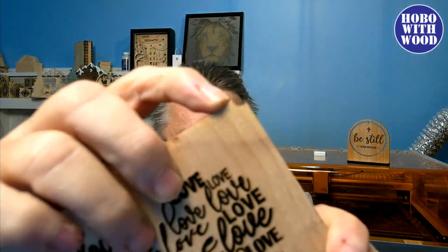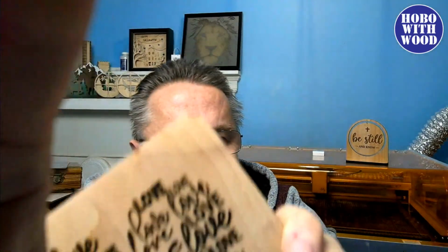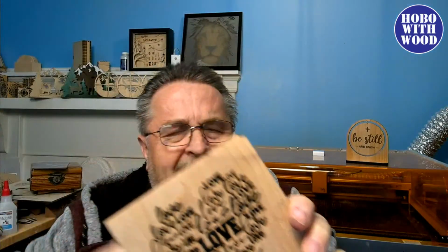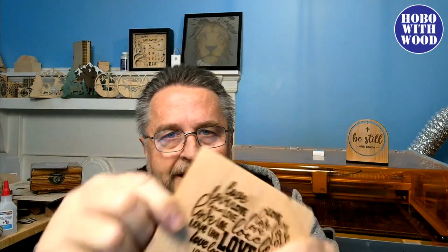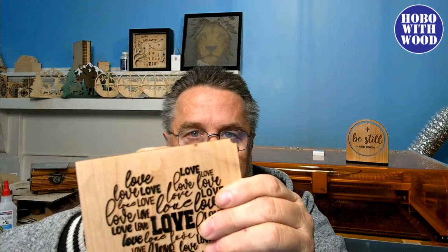So you've got to test. In fact, when I put this material on the laser bed to find out what I needed to do, that's what I did. I went right up here in this top corner, and you can see there's a little semicircle cut out of there. I did a test cut to find out what it was going to cut. Well, that's what I needed to cut this side. I didn't test this side because I didn't think I would have the same problem again. I've already made several of those, and I had not run into this issue. But I ran into this issue tonight, twice. So now when I'm working with this maple, I know I need to do a test cut here and do a test cut on this piece and see if I'm going to have the same results or not.